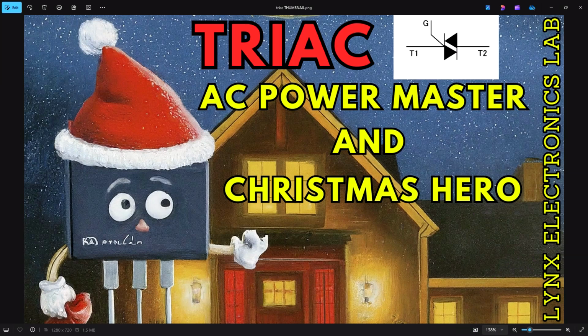Now, a Triac is a type of thyristor. You can kind of think of a Triac as a transistor for AC, where we know that normal transistors are DC devices and will only conduct current in one direction. A Triac can conduct current in both directions. Now, it has a few little weird characteristics, so we'll get into that.